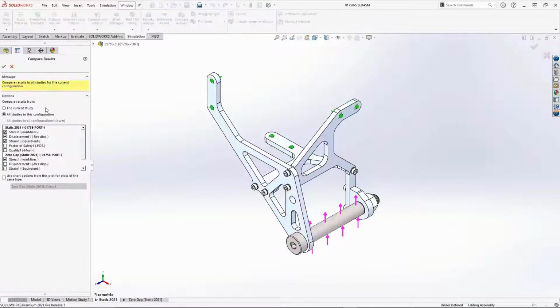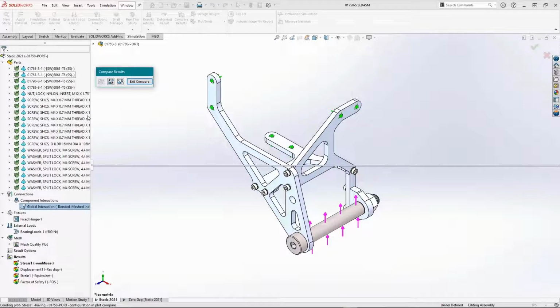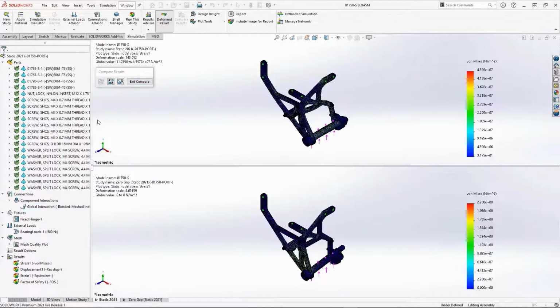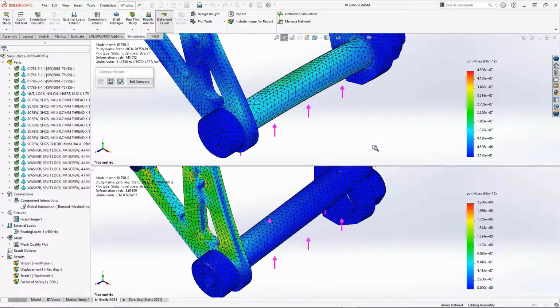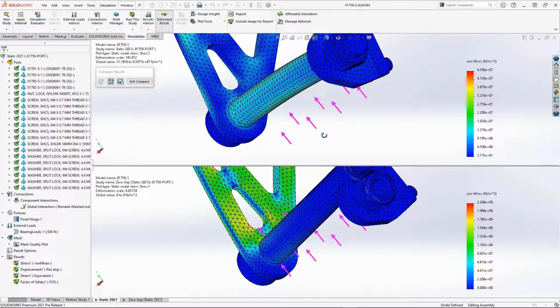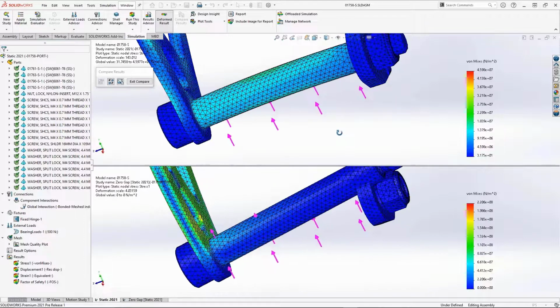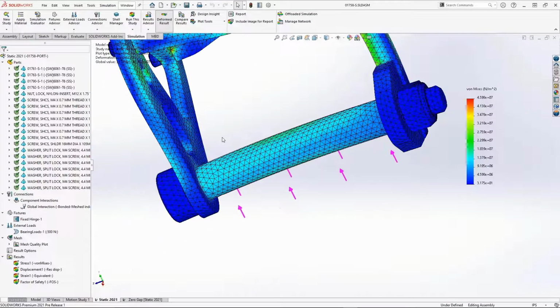For example, with this new property, there's different clearances here between the bolt, the nut, and the plate, but they're automatically recognized, meaning I'm not troubleshooting a model as unstable message, or looking at this comparison here, returning some inaccurate results where a contact wouldn't have even been picked up in the past due to that gap. The results and interactions are actually more accurate as well.